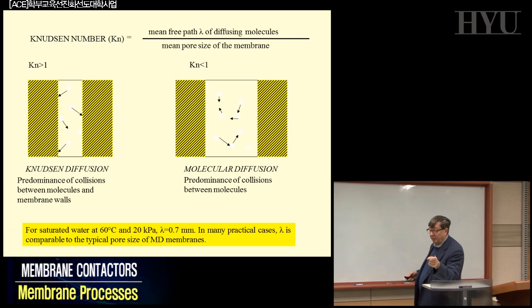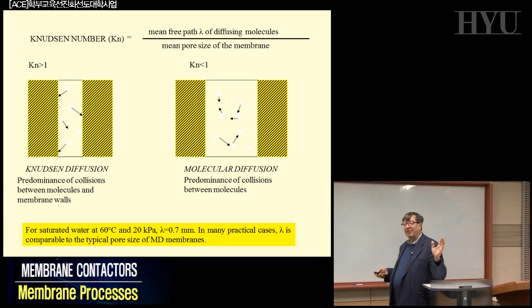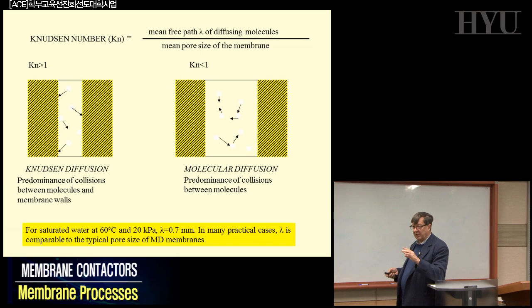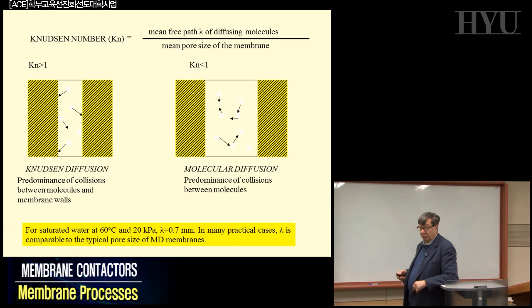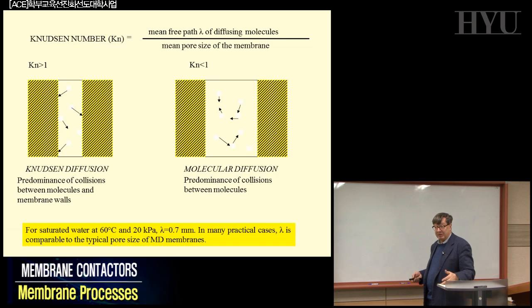If you do this kind of analysis, the conclusion is that mass transfer resistances are basically not very important. They don't control the driving force across the system. It's totally different than in reverse osmosis, where the boundary layer, increasing concentration, decreases the effective driving force, delta P minus delta pi. Delta pi is increasing, delta P minus delta pi is decreasing, and the flux is proportional to this term. So concentration polarization can kill completely the process.